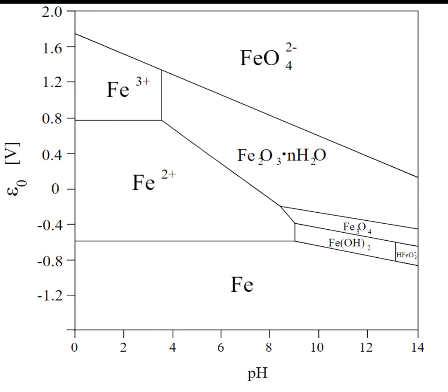The interesting thing about iron is if we go up in pH, it becomes more stable. At high pH, iron doesn't really have a window. There's a little tiny iron here, but most of the time it's stable up to here. Then it becomes soluble as this other iron anion. If we make it really acidic, so if we're right down at really low pH, then we have no chance of stabilizing our metal at all. It isn't stable at all. So we don't want to go in that region, or at least iron is never stable down there.